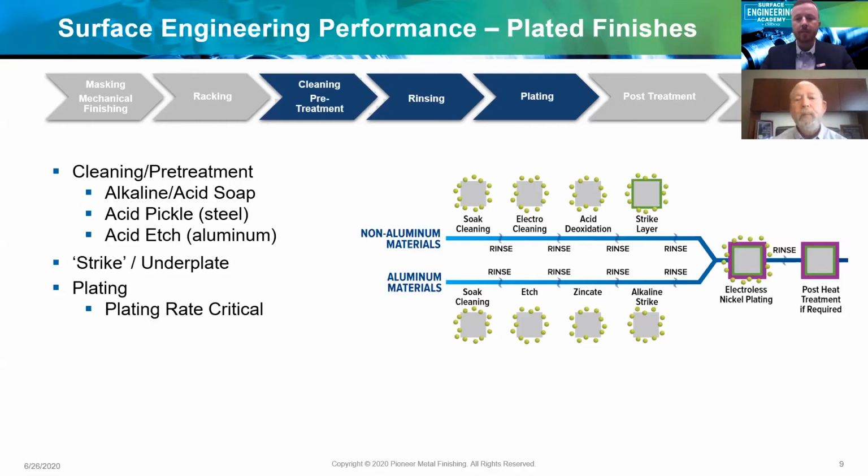Yeah, so Steve, if I really had to sum that up, I mean, cleaning, pre-treatment, making sure we don't have any disruptions at the surface for the positively charged ions of metal to be deposited on and form a good, strong bond and really drive the adhesion process. So yep. Pre-treatment cleaning and avoiding any sort of embedded material, of course, as you mentioned, or dried coolant, those are always immediate red flags for any metal finisher, quite frankly.